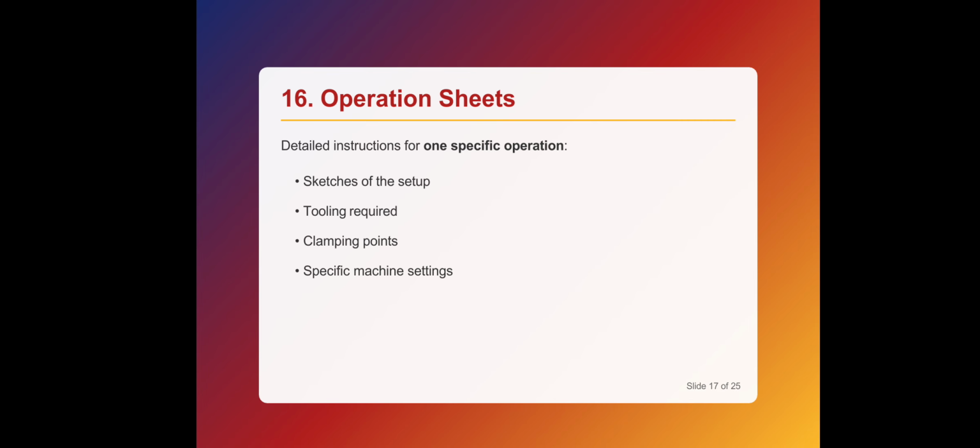Example: component number, drawing, name of the component, material, quantity to be completed on, routing section, machine, operation number, operation description, tools required, fixtures and other accessories, time to set up operation, and total time required, etc. These are also involved in the operation sheets to provide a record for future job coding, cost estimating and standard costing systems, to act as a vehicle for communication.